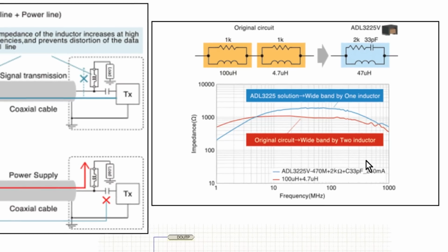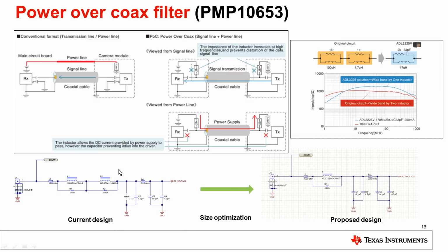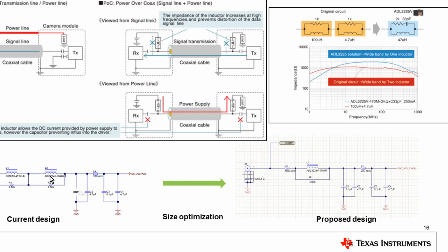and you'll see a decrease in the impedance. Now what's the solution here? The solution here is to add another inductor in series, which is actually a 4.7 microhenry inductor. What it will do is ensure we have high impedance over a wide frequency range of interest. But if you use these two inductors in series, the size will become unmanageable. So what is the solution?